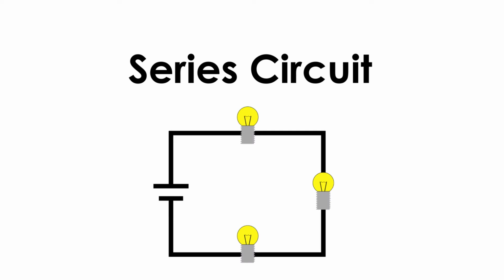When items in a circuit are linked end to end in a single line, they form a series circuit. In circuits like these, current flows in a single shared path. Voltage from the power supply is divided across each resistor, and the resistance total for the circuit is the sum of the individual resistance from each resistor.